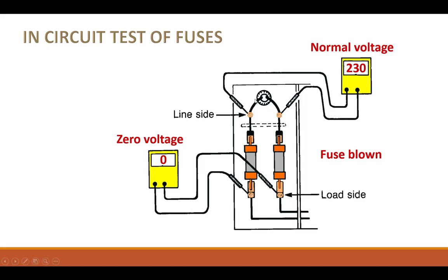This is important. This is why we've talked in the past about what's the voltage across an open circuit, what's the voltage across a short circuit, why is it like that? Understanding that really helps in troubleshooting this type of situation, which you will encounter a lot of times. When things aren't working down here, when this load doesn't work, one of the first things you look at is right here.